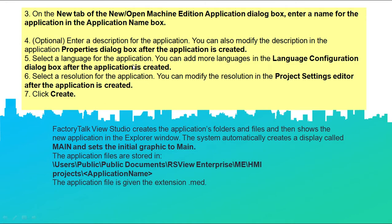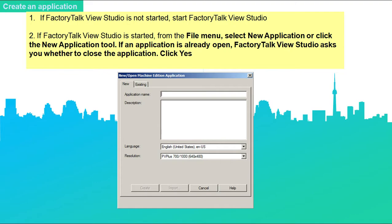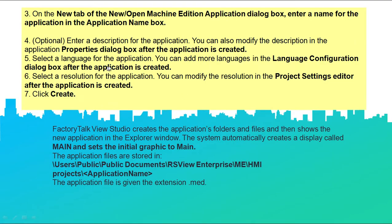On the New tab of the New/Open Machine Edition Application dialog box, enter a name in the application name box, which is very important. Then there are optional things: enter a description for the application. You will find the description field there. There is also language and resolution. Select a language for the application. You can add more languages after the application is created. This is another utility there. Select a resolution for the application.